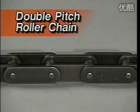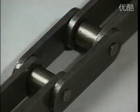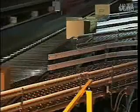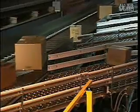Double pitch roller chain, also known as extended pitch chain. The dimensions are the same as standard roller chain, except the pitch is doubled. Because a given length of double pitch chain contains only half as many pitches, it is lighter and less expensive than standard roller chain, and it is especially suitable for long center distance applications.